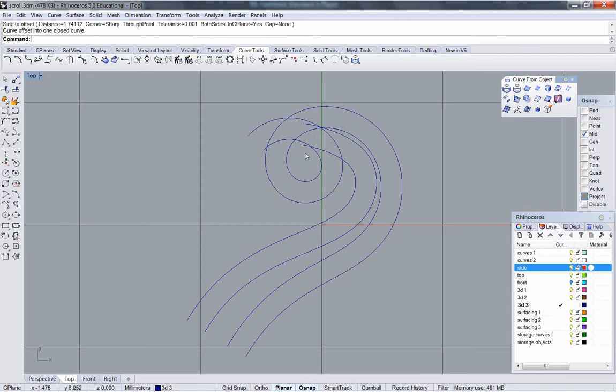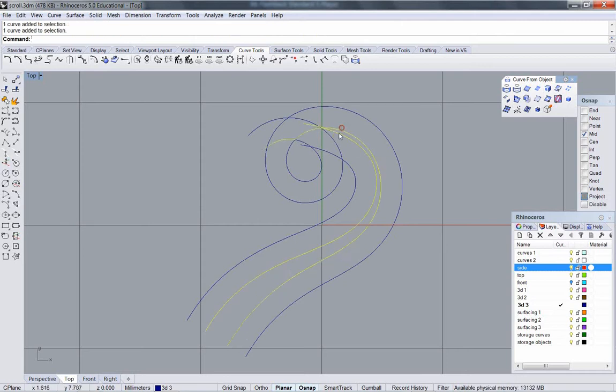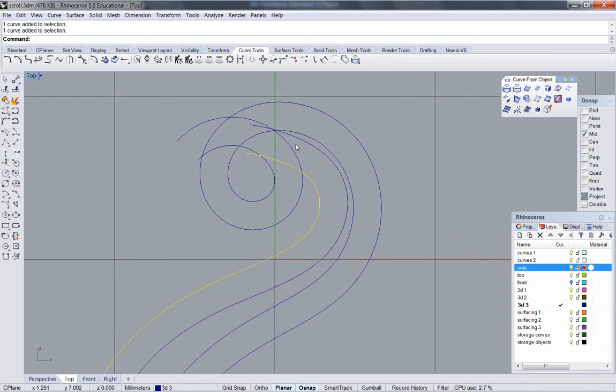Okay. So now I have these, but I do have this closing off here, which I can't have. But since I've had history attached, I can turn on the control points here. And just like we did with our filigree project, I can play with this. I like the curvature into here, so I don't want to mess with that. And I would like this to be a nice sort of form coming in. I don't want too hard of a corner because I know Rhino hates to do fillets around a really hard corner.